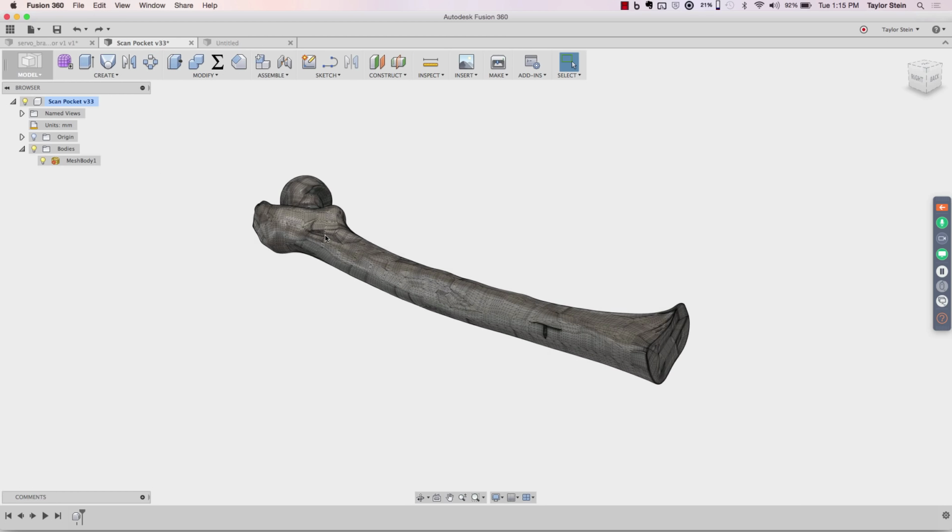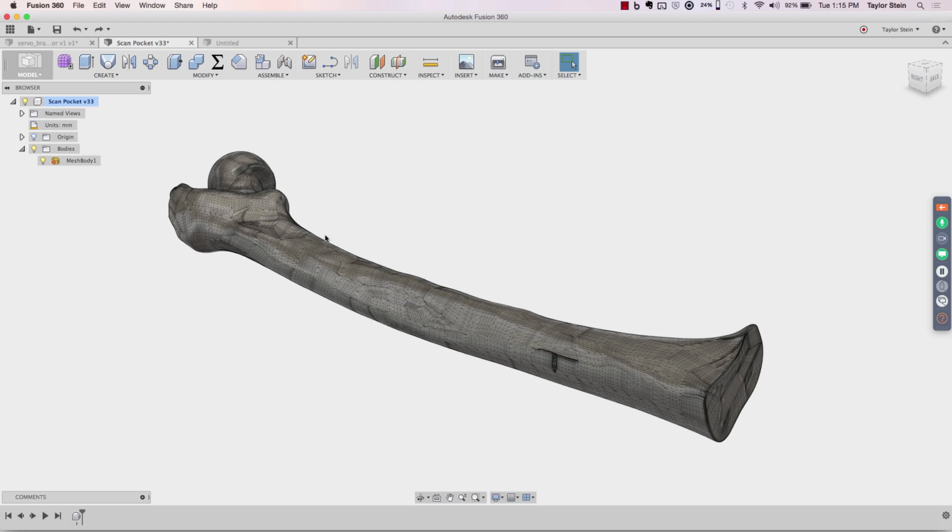And what we can do inside of Fusion 360, and it really depends on the geometry that we've imported as the STL, is there's a really interesting command inside of the Sculpt workspace that allows me to snap down T-spline points onto an existing mesh. So to show you how that works, I'll go ahead and create a new form.